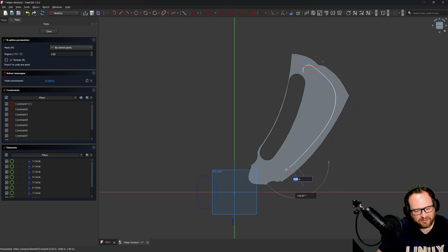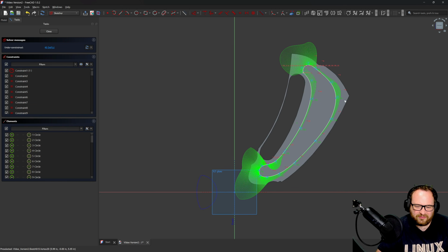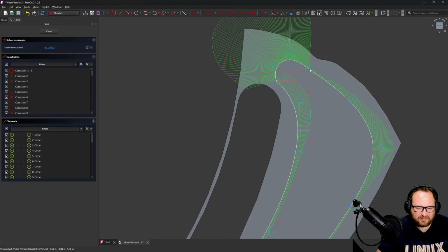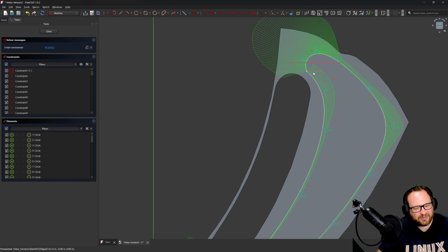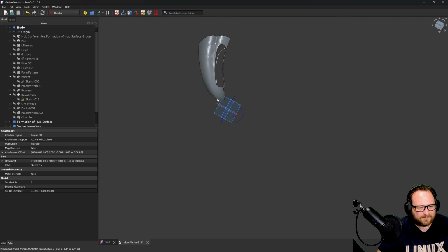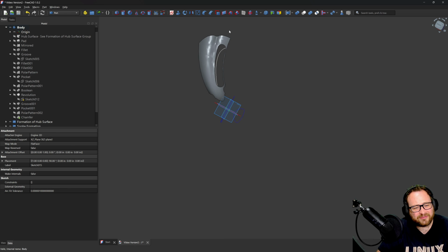I think how might I want to wrap a surface around this face that would look pretty interesting. And just like that, I think we've done it. I'm going to move this guy a little bit further out. Yeah, I think that looks not too bad. Smooth, non-constant radii, very interesting. So we're going to close that. And we're going to go to the part and extrude. We want to extrude a surface, not a solid.